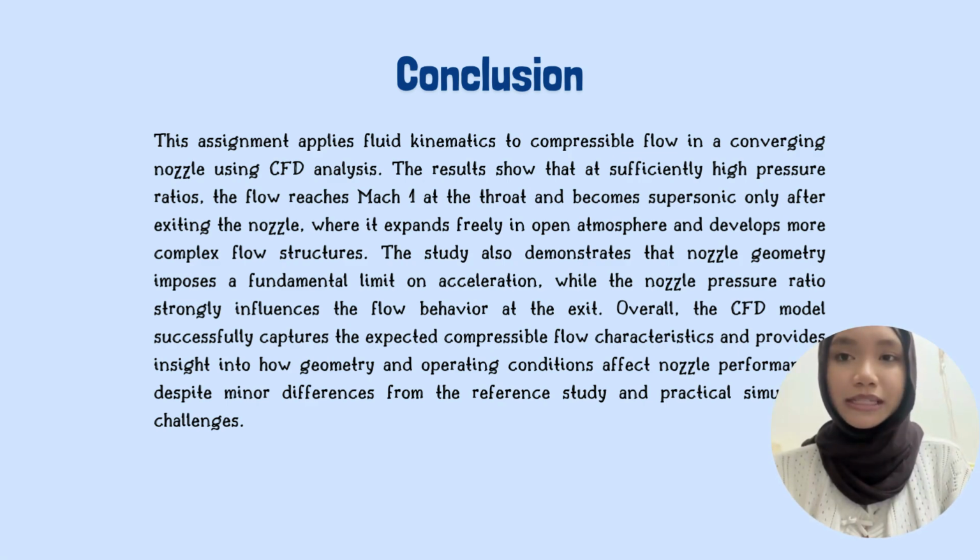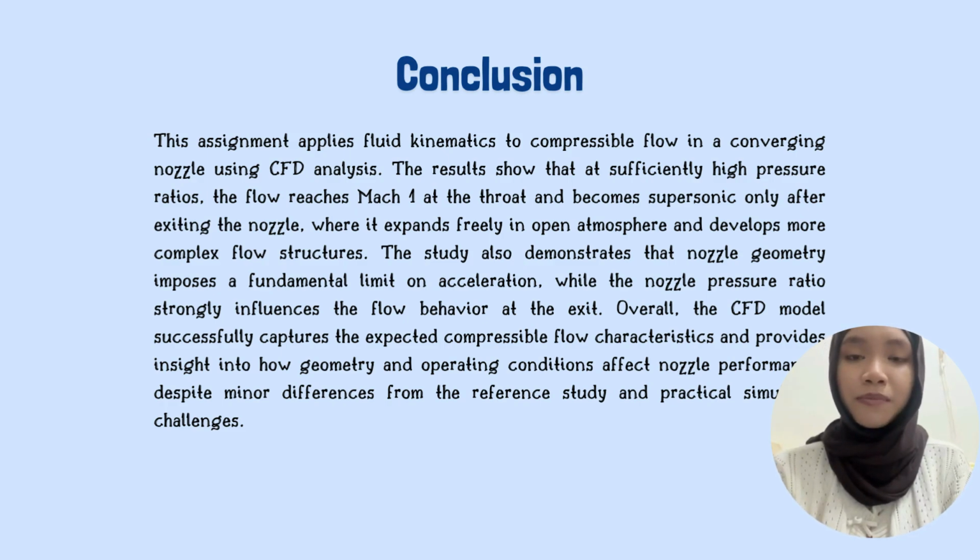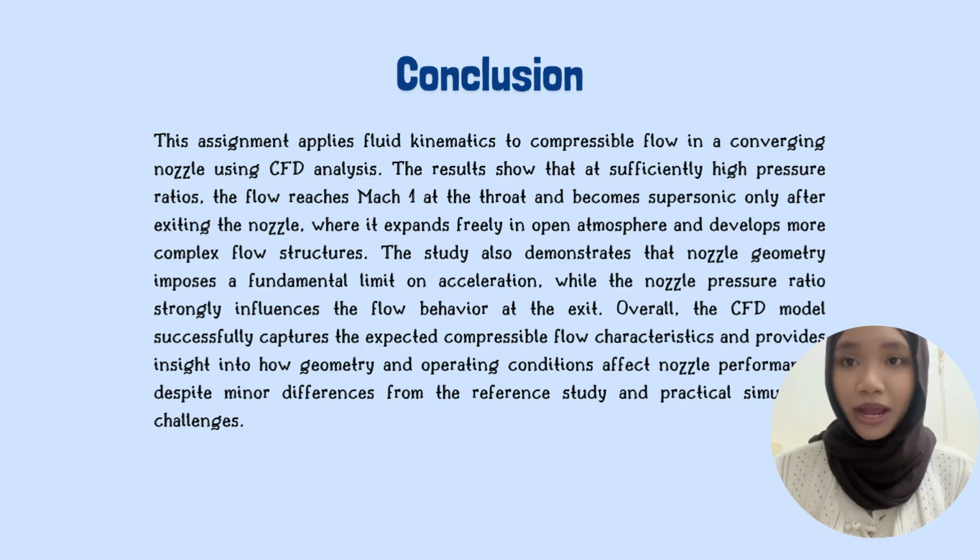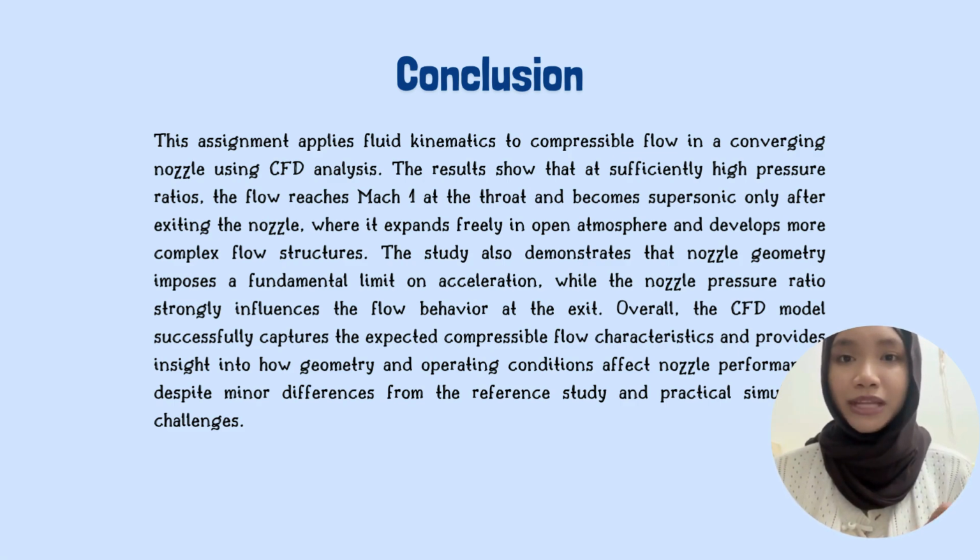To conclude, this assignment successfully relates the concept of fluid kinematics to compressible flow behavior in a converging nozzle. From the simulation, it is observed that when the pressure ratio is sufficiently high, the flow reaches Mach 1 at the throat and becomes more supersonic only after exiting the nozzle, where it expands into open atmosphere and develops more complex flow patterns. Using computational fluid dynamics, the flow behavior was analyzed and compared with published literature.